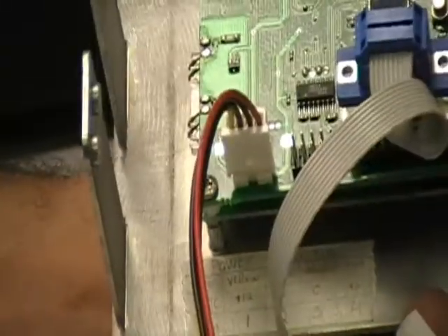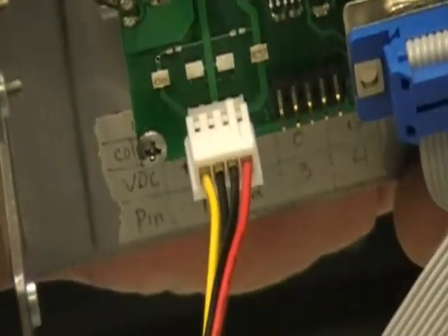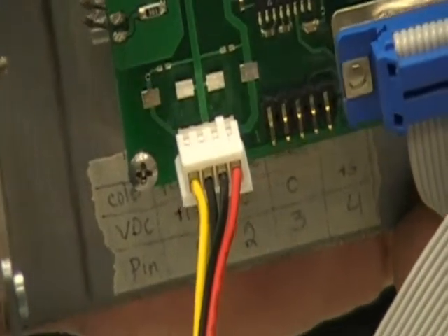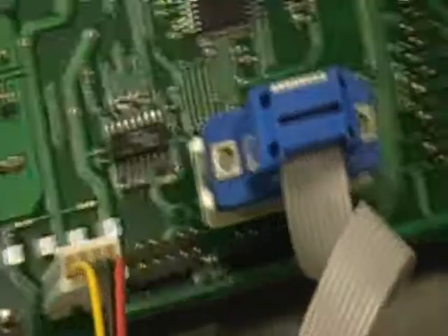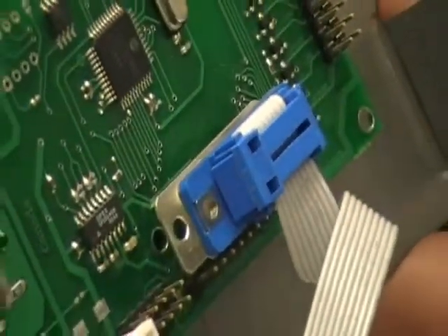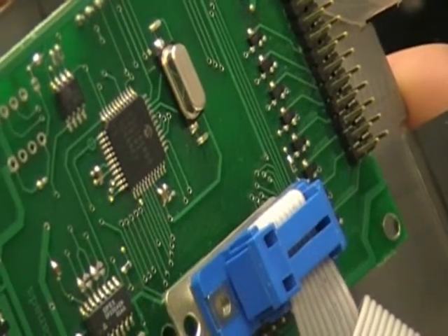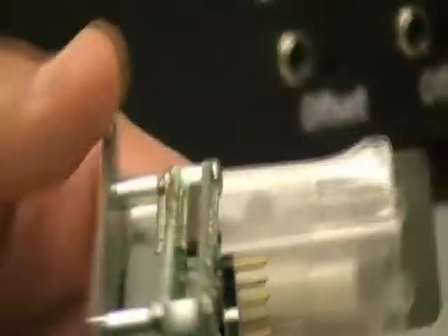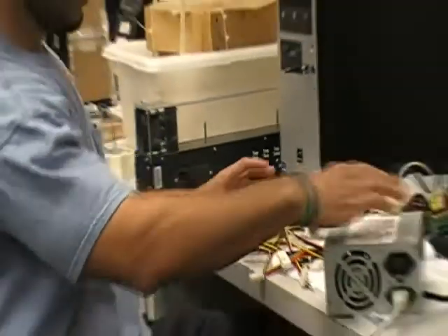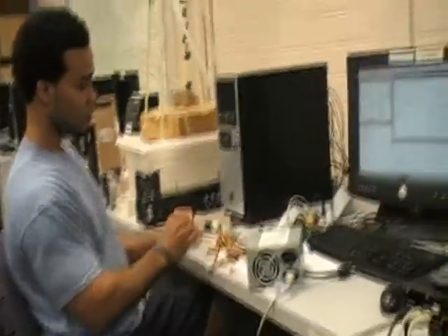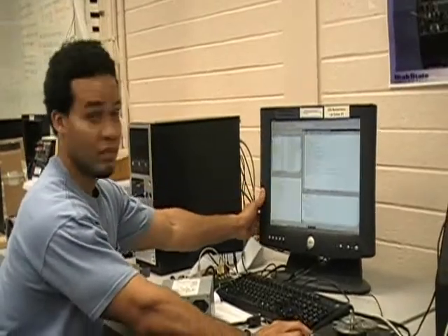The order is written here, which you can find in the manuals. It says yellow, black, red on that strip. If you don't do that, it will burn, so please be careful, and hook this blue and white RS-232 cable to the back of your computer, and that's it. You're all set. And you will get some code from the TA of this class to run the LCD.